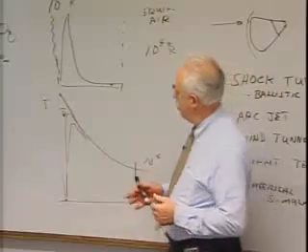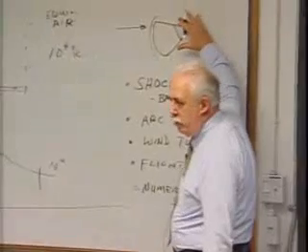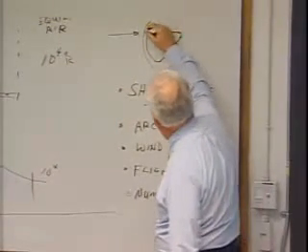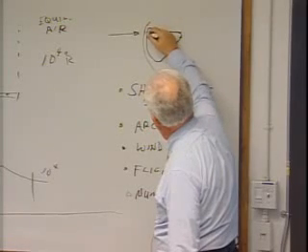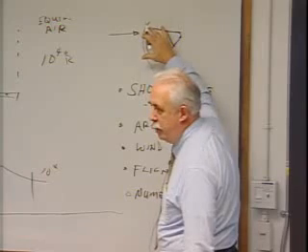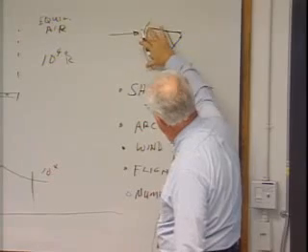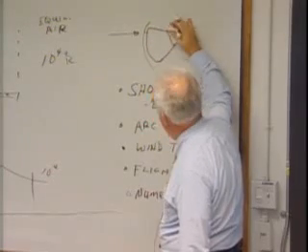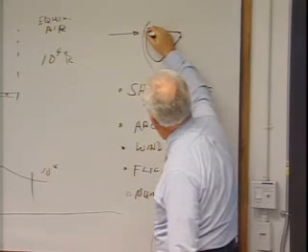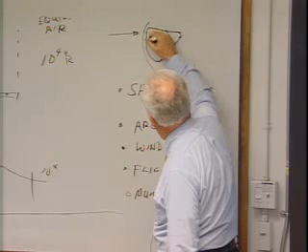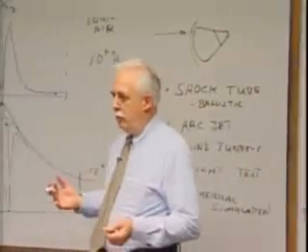And frankly, I'll show this in charts, in terms of the design approach to getting the aerothermodynamic environment at flight, we used the same technology that we used in Apollo, and that was we take a scale model and go into a wind tunnel. Now this is a blunt vehicle, and so if you look at it as an inviscid flow, the close to normal shock entropy is basically the entropy of the entire body, inviscidly. And so the normal shock or strong shock gas dominates the flow around the vehicle. As you go to low angle of attack, you get into an entirely different situation. In any event, what happens in terms of the wind tunnel heating here compared to different distributions is all pretty much proportional. And that's fundamentally what we used.